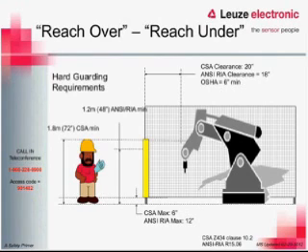If we have a guard at 72 inches tall, we can be 20 inches away from the hazard. ANSI RIA is 18. This is all, of course, assuming that it is mounted 6 inches off the floor per CSA, 12 inches off the floor for ANSI and RIA, and for active optoelectronic devices such as light curtains, 12 inches is the standard we go by.